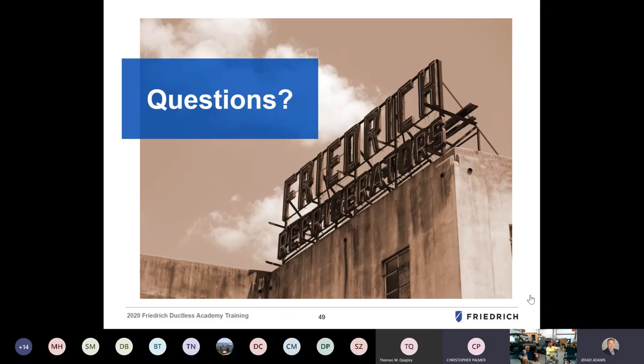All right. Thanks, Mr. Palmer. Great answer. I think as an OEM, we always appreciate a double or triple evac. Oftentimes, when we get a call into technical support, we lead with that question: how many times did you pull an evac and how many microns did you hold it to? So I appreciate the answer.